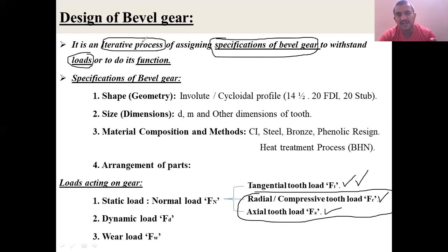Now, design of bevel gear is nothing but an iterative process of assigning the specification of the bevel gear to withstand loads or to do its function. What is its function? The function of a gear is to transmit both motion and power from one shaft to another shaft. These are the specifications.